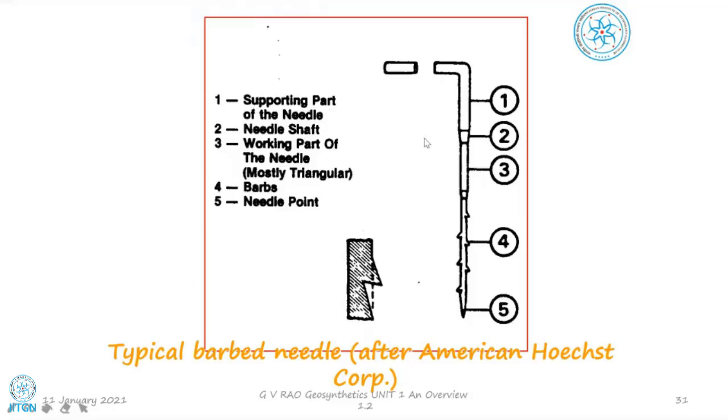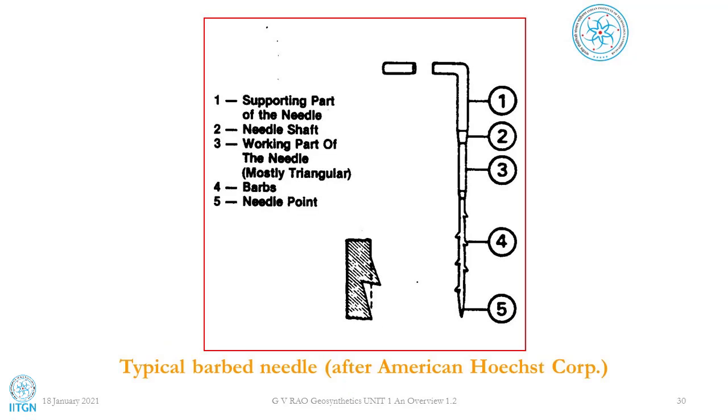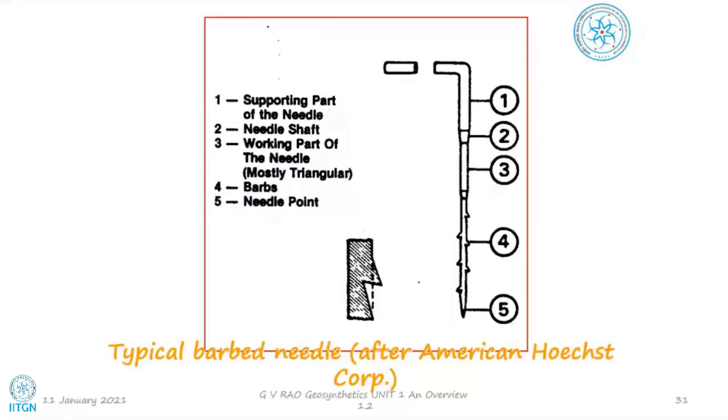We'll see that these needles we are talking of are not normal needles. So you can see this. The needle has got a projection. I mean, I'm just showing you one element now. These were projections. So normally when you talk of stitching in a normal sense, what is happening? We got a needle. The needle is very smooth actually, very smooth, very fine. At the end there's a hole which is called the eye, and the thread which you are going to use for stitching your buttons or repairing your shirt naturally gets into the layers of textile, let us say. So the binding is happening because we made a hole and then left the thread in between continuously by some process, manually or otherwise.